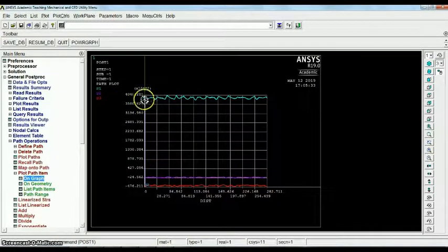As you can see in S1 plane, which belongs to X directions, the highest value 40 Newton per millimeter square, and the minimum in Z direction, and then Y direction also less, and it's both in minus, means both compression, while it is tensile here, tensions here in S1 plane.